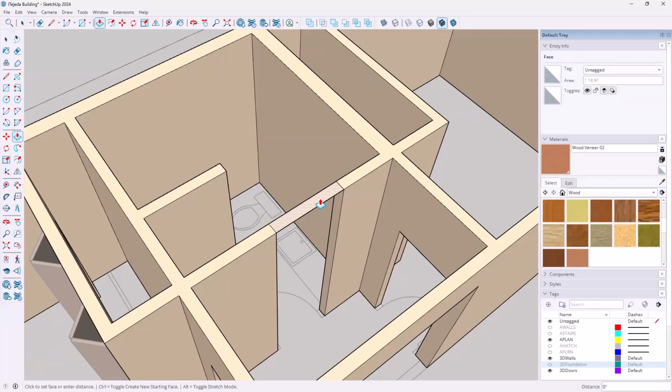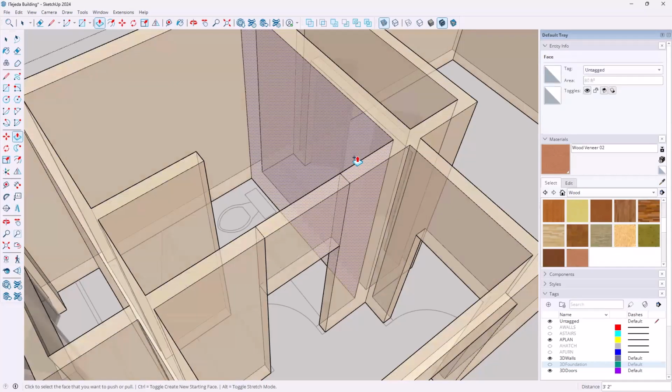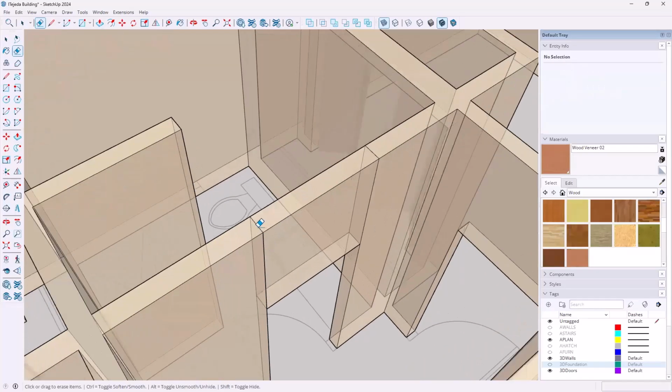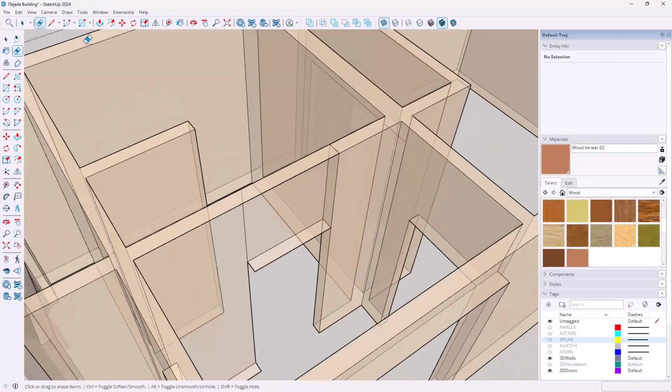I want this surface. I'd like to take it straight down, but notice it's leaving a hole there. So tap the control key. That way it's going to make a copy, and then just let it align to that endpoint. Got it. Then switch over to X-ray, type E for erase, and start erasing. And be real careful. See how I still have my AutoCAD layers on? I'm going to turn that one off. That way it doesn't get in the way. And then erase. And I erased one too many lines there, so let me edit, undo, erase.